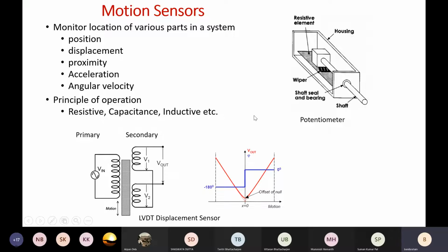And obviously there are other special types of materials or sensors which can show other properties, so they may not be directly resistive, capacitive, inductive, like piezoelectric, triboelectric. Those we will see later on. So effectively, in a more conventional approach, I can convert the physical quantity into an electrical quantity by some resistive, inductive, or capacitive mechanism.